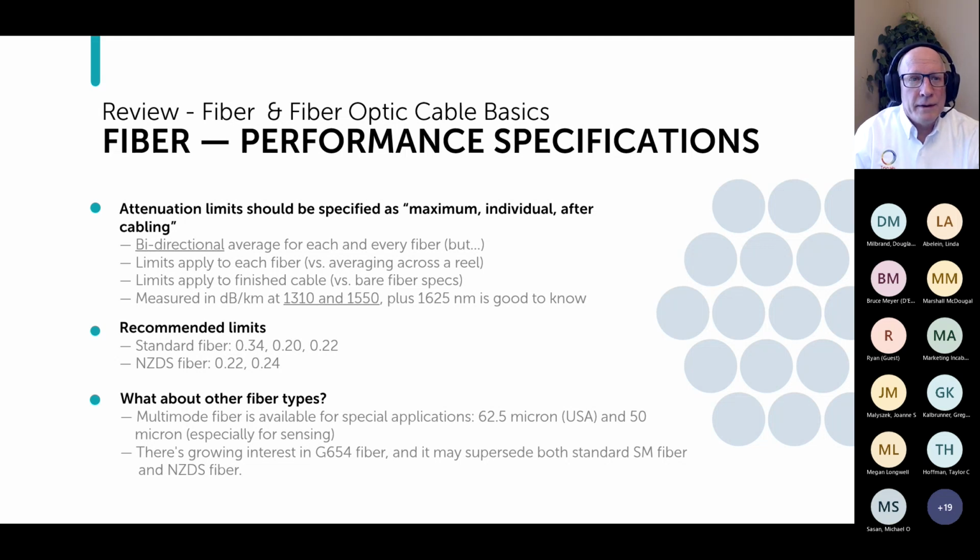A dielectric line, an extrusion line, is going to run about a factor of 10 faster. So for every 1 OPGW reel you produce, you're likely producing 10. And so that kind of overwhelms your testing capability. That's why the cable manufacturers have migrated towards outside in testing, especially for dielectric cables. But as I said, I'm old school for OPGW.